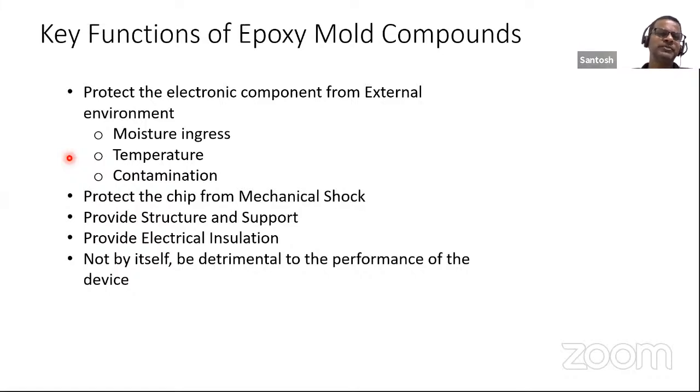Okay, so here are the key functions of epoxy mold compounds. As you expect, the IC chips are very sensitive, very delicate. So the first thing is the electronic component needs to be protected from the external environment, from moisture ingress, from temperature, and from contamination. So that's the first function of the epoxy mold compound.